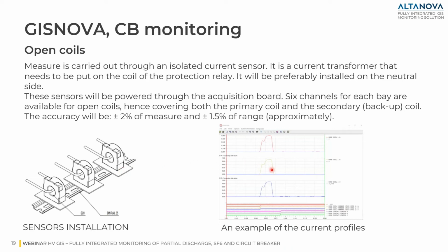In general, in faulty conditions, the circuit breaker parameters become outside the OEM's recommendation, for example showing deviating profiles. If you look at these profiles, for example, they require more time to complete the change of status, or a command coil current stays for a longer time, or the velocity is lower than nominal.